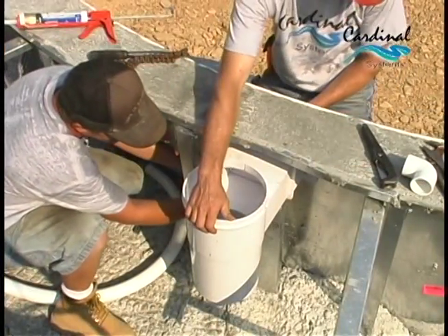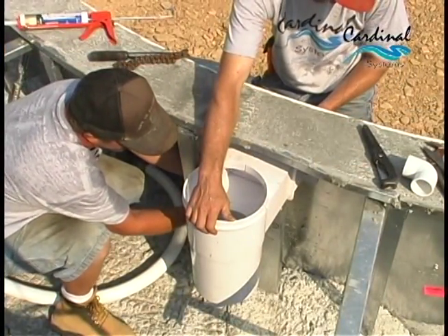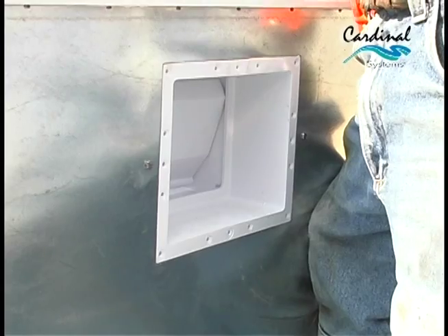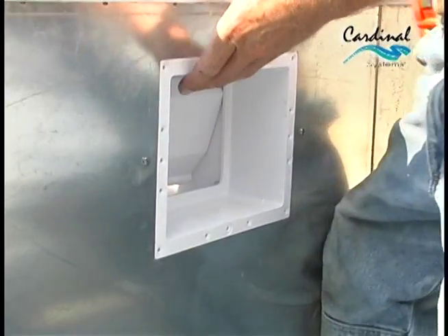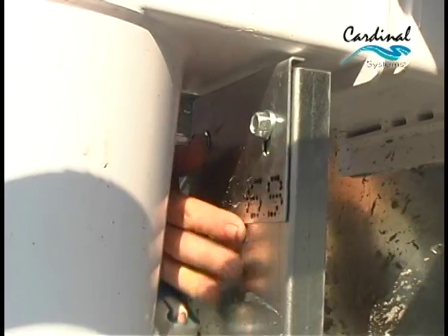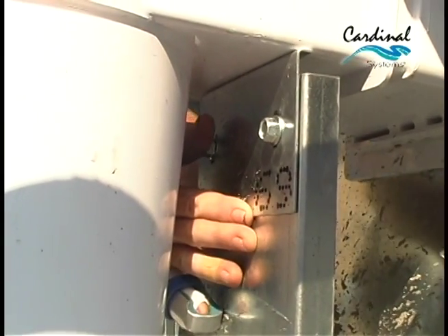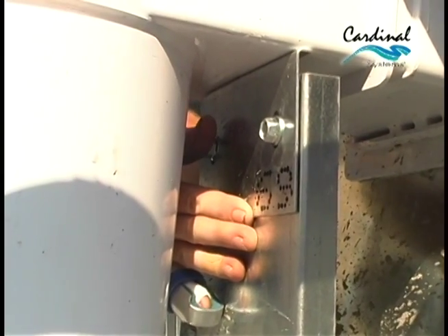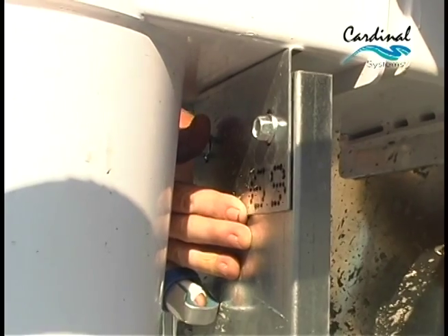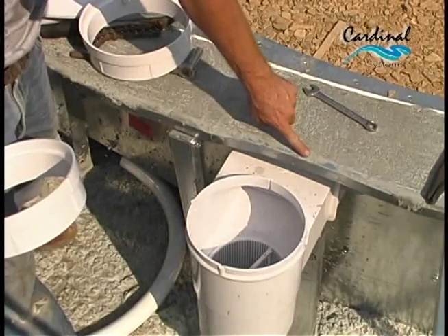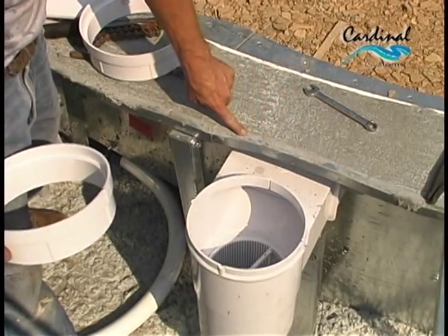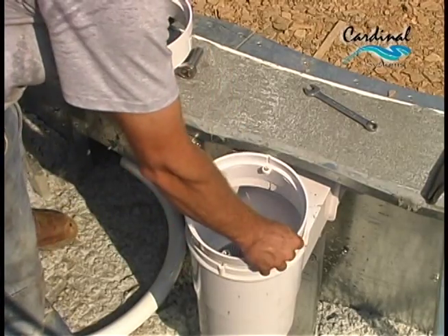Before plumbing the skimmer, adjust the skimmer support system to take the weight of the skimmer off of the in-wall portion. Simply push up on the fixture until it supports the weight of the skimmer, and tighten the nuts. Notice the stone coping support around the skimmer has been indented to accommodate installation.